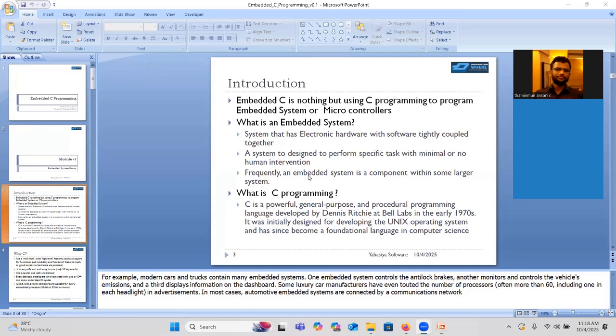Similarly, how are these LCDs interfaced? They again have IO interfacing. There are many ways to interface them. We can interface an LCD through which you can send the required data signals to it. Again, you have to study the data sheet of that particular LCD or TFT display. According to that, the controller should generate the input. When such inputs are generated and fed to the display, it will display the text message that you want to display.